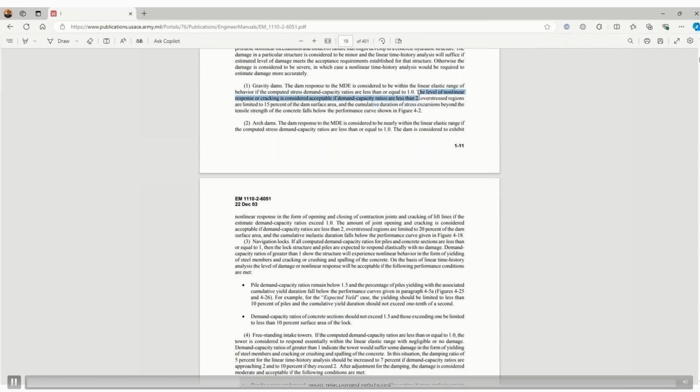Okay, for one particular node, say in a dam, in one particular time cycle, maybe some higher tensile stress, more than 2 times higher than the allowable tensile stress, is induced. Maybe in another cycle it is reduced again to less than the allowable. That we have to check, how much duration that particular node is overstressed.